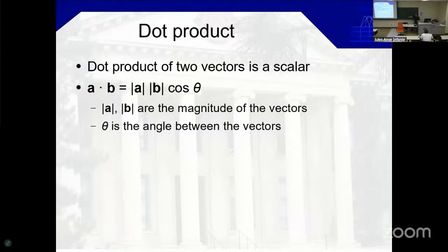Now I can use the unit vector of AB times the vector EP at P1, which is EP minus E0 and P1 minus N0 and 0. So I have now a second vector. This one, the unit vector, I calculate once. Even if I have 200 points in between these 2 points on the station, I calculate only the unit vector once, and then I can just do the vector multiplication, the dot product.